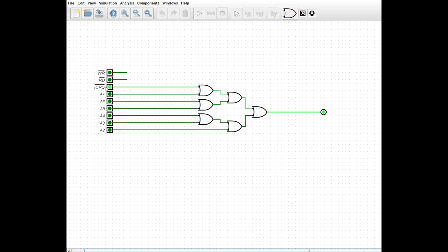There may be some chip select signals out there that require an active high, but if you need it, you can always put a NOT gate on it, use a 74HC04 or something similar, maybe a 74HC14, a good Schmitt trigger. So lots of options there for you to convert that signal if you need to. But this is the basis for everything that we're going to be doing. And we've got a total of, I think, 9 different chip selects we need here.